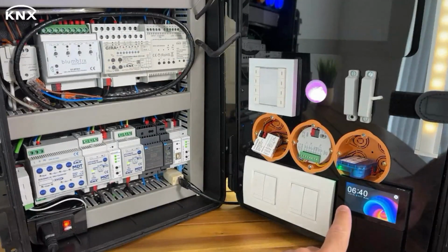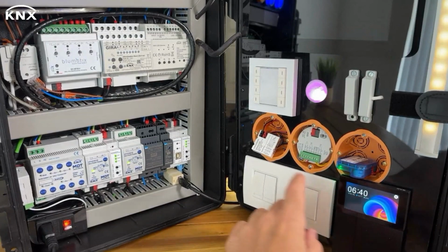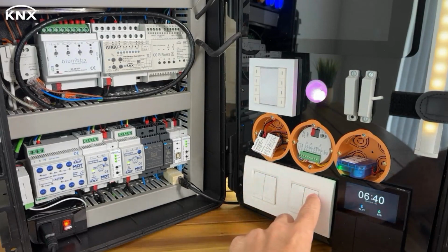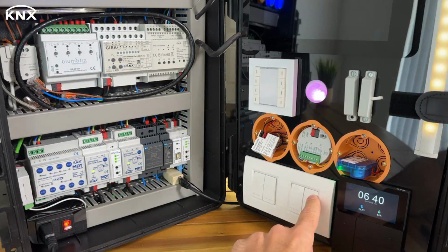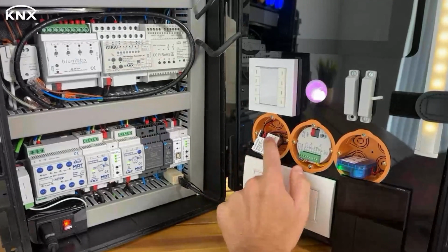So we have here, for example, a KNX keypad. This is a binary input to integrate non-KNX keypads. These are European style, but forget about that. We can use US style, Chinese style, whatever we wish. At the end of the day, it's going to be a relay, open close. So we integrate through this binary input and we convert this into KNX.